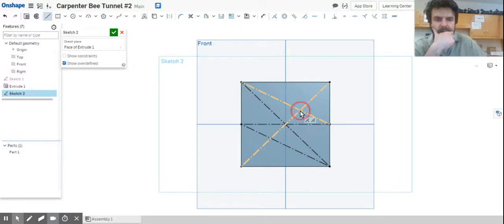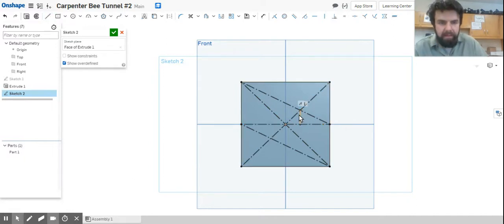Then what that does is we can take a line here and go straight down perpendicular. And there we go. We are a third of the way in. If I was to measure from here to here, this should be 1 inch. Let's try that. Okay, now if I add this dimension, I'm not going to like it, because what I'm doing is over defining. By geometric laws, that has to be 1/3. The whole block's 3, so it has to be 1. Watch. Click, enter. It comes up gray because it's telling me that's not necessary. Awesome. So now we've got the location of our first hole.